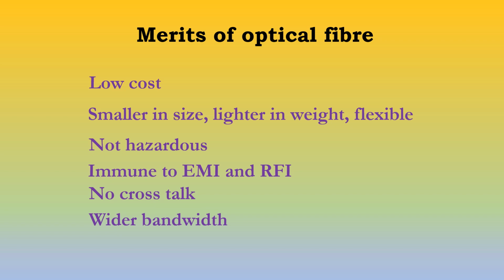A wire communication link could accidentally short circuit high voltage lines and thereby create great damage. Such accidents cannot occur with fiber links since fibers are made of insulating materials. In optical fibers, information is carried by photons. Photons are electrically neutral and cannot be disturbed by high voltage field, lightning, etc. Therefore, fibers are immune to externally caused background noise generated through electromagnetic interference and radio frequency interference.